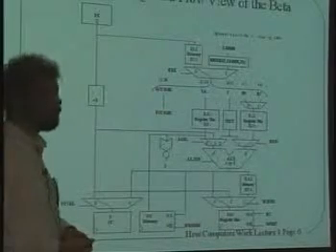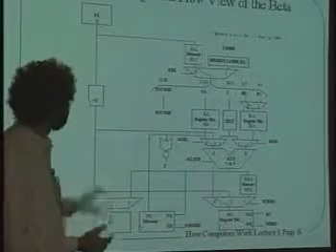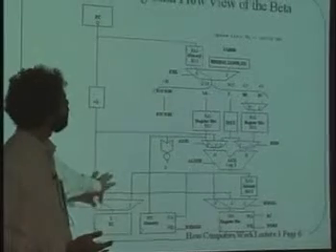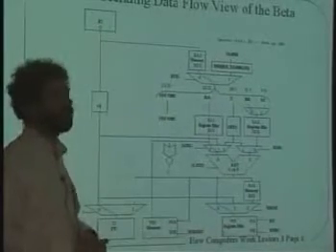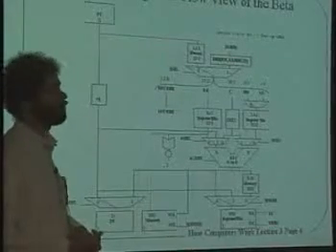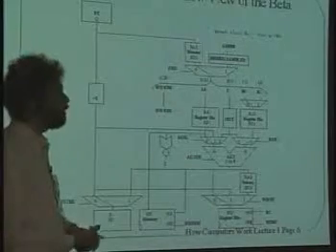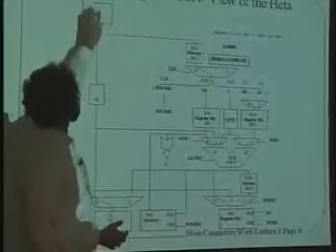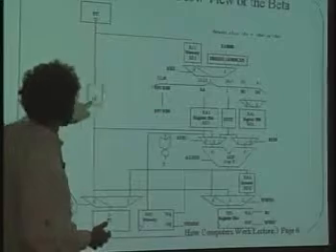And we're going to talk about how those individual parts work, but for now, let me explain that this diagram right here shows exactly how we would do an operation like register C gets the contents of register A plus the contents of register B. And very, very briefly, because I like to say things over and over again, here's how it works. The program counter is stored over here. Okay, that's the program counter register. The output from the program counter comes down here and goes into a module which says +1. So this will increment the output of the program counter, and then that goes down here.